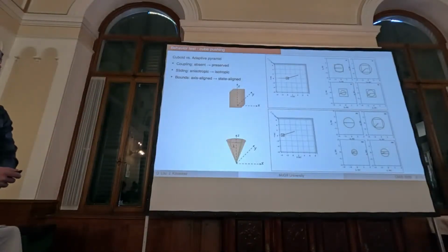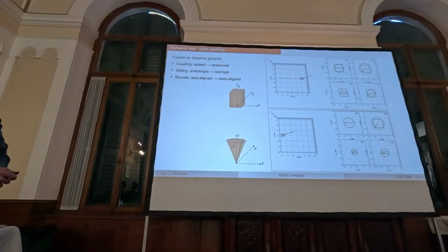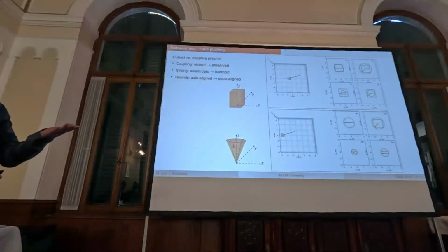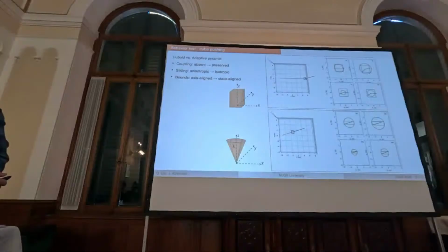When we solve with the classical cuboid model, we can see we have force coupling error, where the resulting normal force and the box have clearly offset. Also, for the velocity, the motion is locked along the box edge direction, generating this velocity anisotropic behavior. When solved with the proposed adaptive model, all the coupling and anisotropic issues have been resolved.